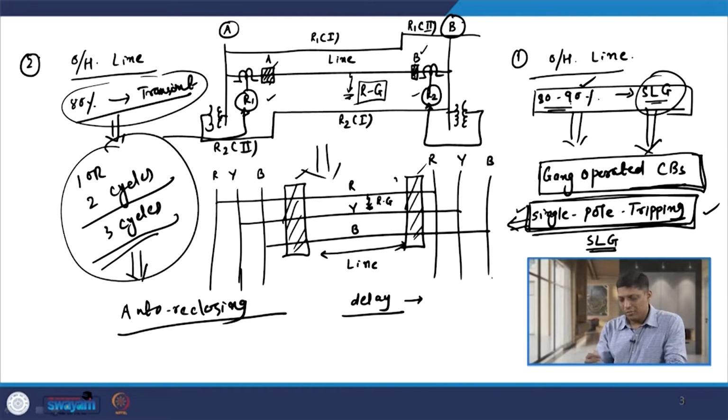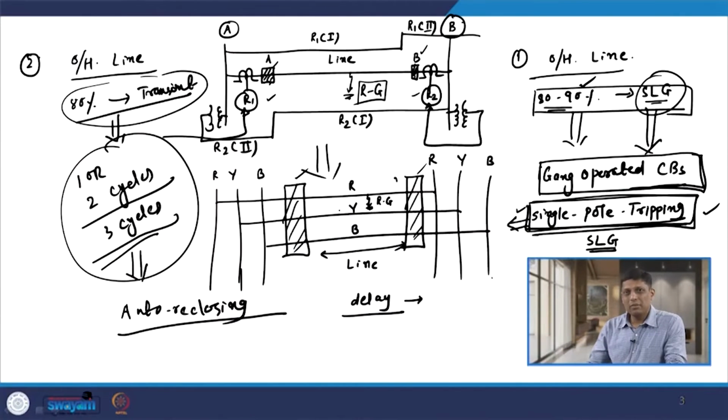So, whenever we reclose it after the first reclosing attempt, such a fault does not persist in the system and our system becomes stable. So, there is no need for any other services like maintenance, because the fault is already cleared. Of course, if the fault is not cleared, if it is a permanent fault and not transient, then again we need to open it, and that is the part of reclosing that we will discuss later when we discuss the auto reclosing and synchronizing chapter after this chapter.